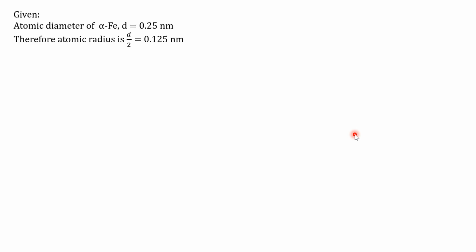So initially what is given to us is a diameter. Atomic diameter is given, then we can find the atomic radius. And for BCC, we know this relationship, right? This is the lattice parameter A0 into root 3 is equal to 4 times R. So based on that, what will be the value of A0? So whatever you have told is correct. So before we go to that, we'll just solve the initial part and keep till the lattice parameter part. So what will be the value of A0?